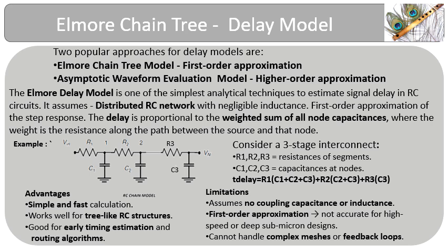The parasitics such as resistance, inductance, and capacitance introduced into a layout are to be extracted to form a circuit model that enables timing analysis. There are two popular extraction models used in VLSI design, namely the Elmore and the asymptotic parasitic extraction models. The Elmore model focuses primarily on parasitic resistance and capacitance and ignores inductance. It is intended for moderate-speed, RC-dominated interconnects only.